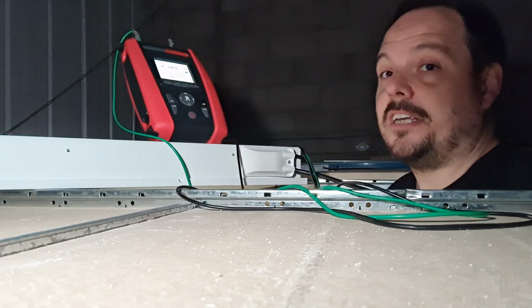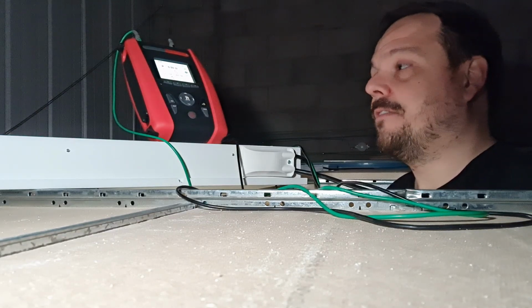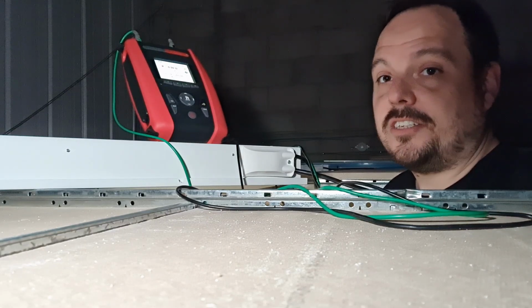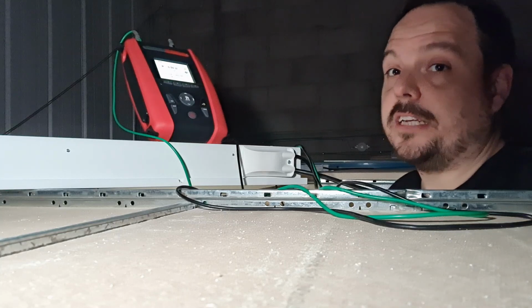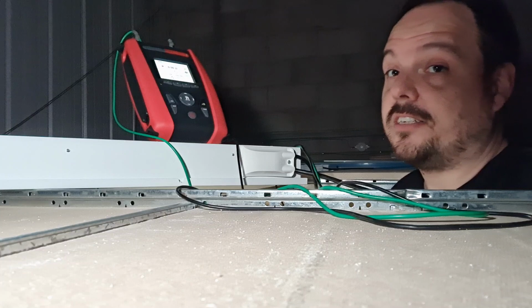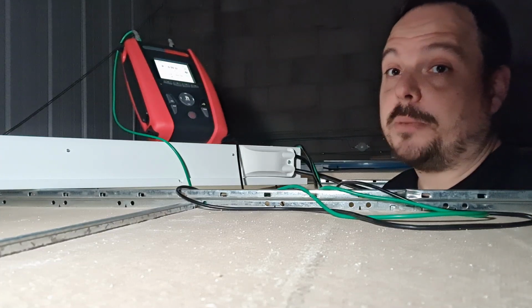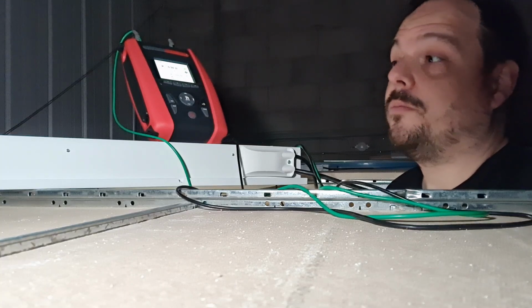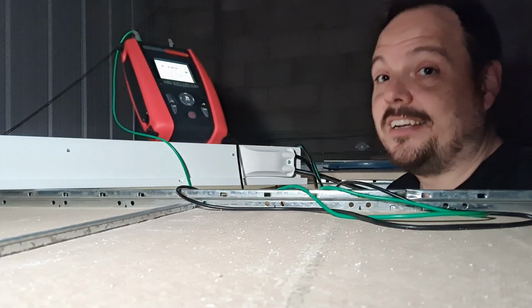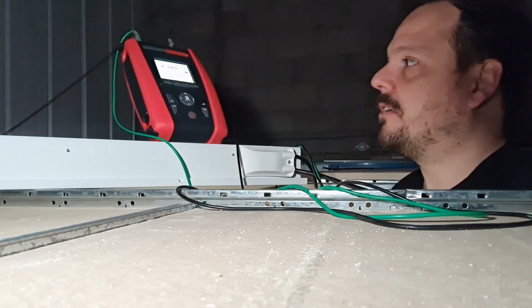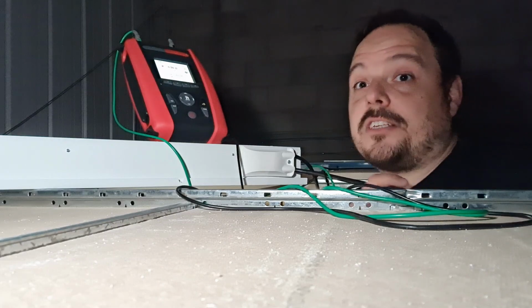It's one of the things I want to keep getting over to people, that this is a valuable test measurement we can take. It helps us understand parallel paths in the earthing system and the effect they're having on the installation, and it also ensures that we haven't made any mistakes during the dead testing, because as you've seen, I've had a lot of that bought apart now, so I can go and put all that back together, and it's a final check that after all of that we have electrical energy at the light fitting and an earth path that's safe. So I'll go and get on with tidying the distribution board up, get the power back on. I might as well leave all this here because I can come straight back to it and get my live measurement. Just bear with me 5 secs.